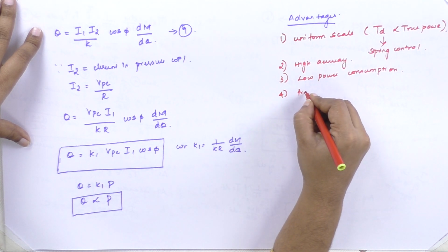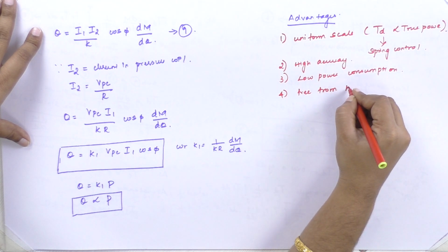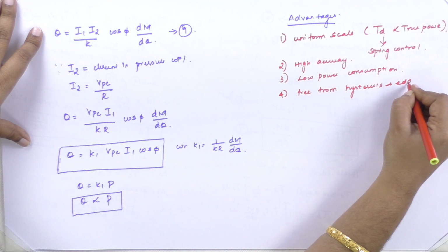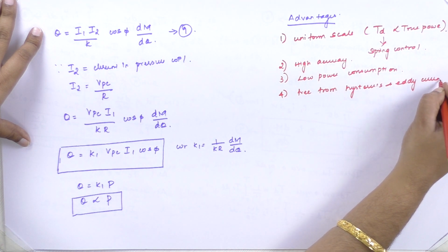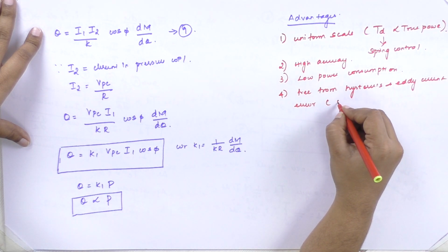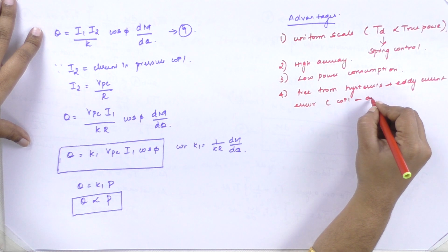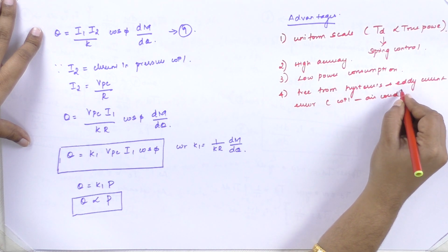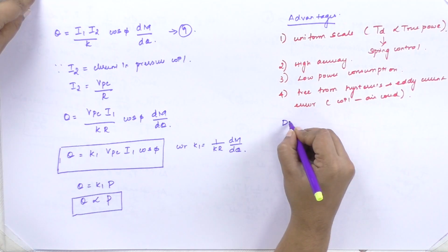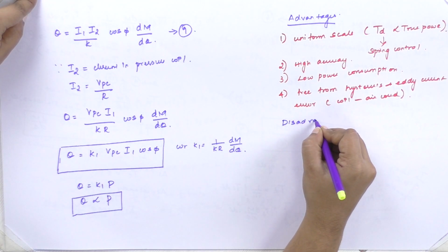It is free from hysteresis and eddy current errors because we have used the coils which are air cored, so that the hysteresis and eddy currents are reduced. Next we will see the disadvantages.